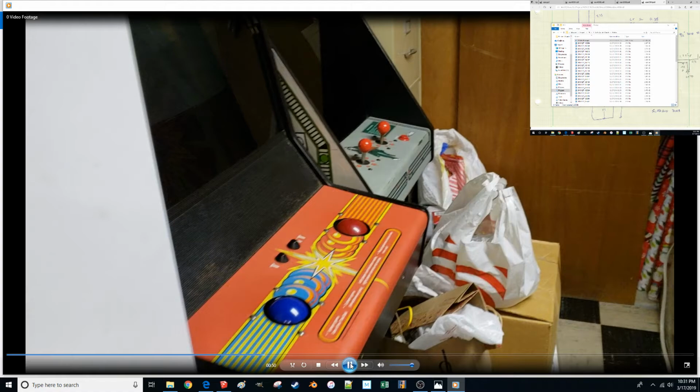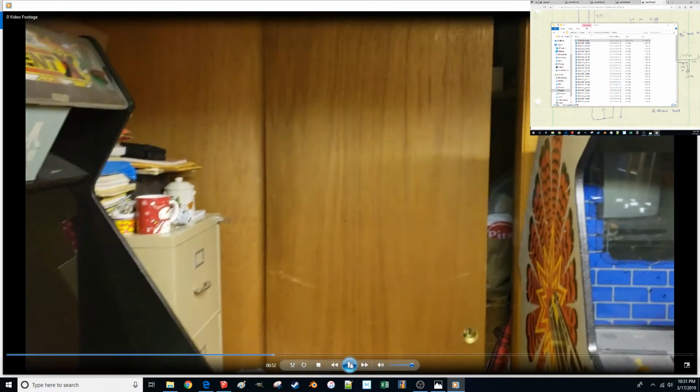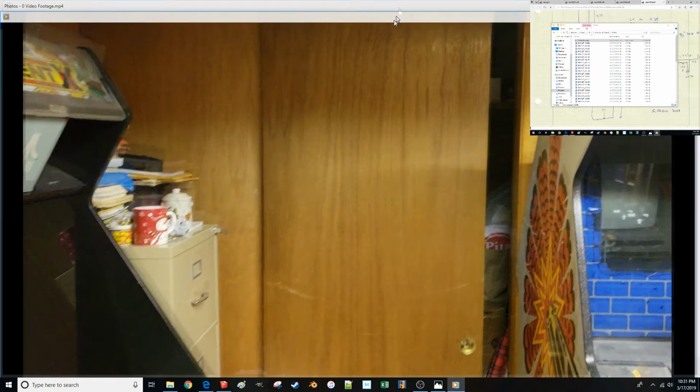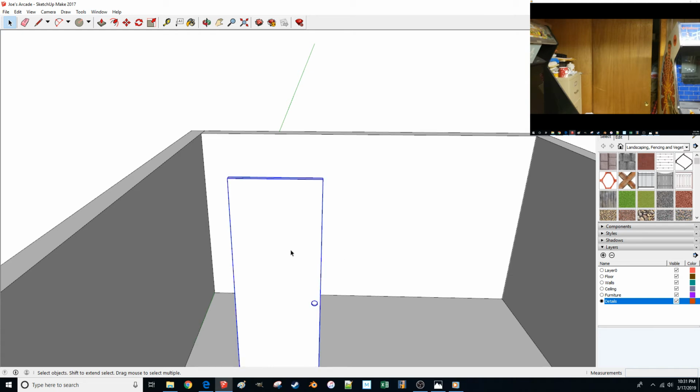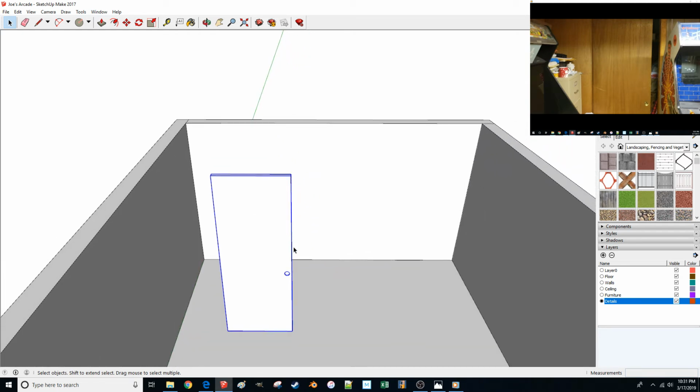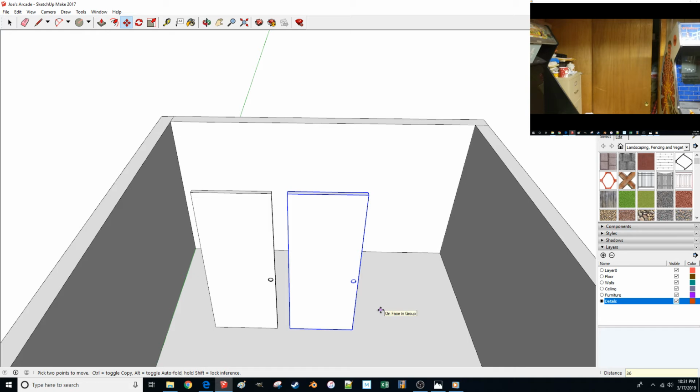There we are. So that's what I'm currently working through. And so if I had to guess the way these doors typically are, there would be a mirrored version of this door here with another pocket to get your hand into. And so I'm going to kind of sneak over and let's move this thing. I'll do a control move so that I can duplicate it. Let's just bring it 3 feet out like that.